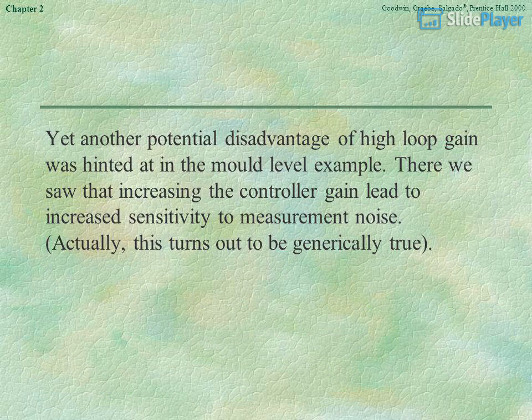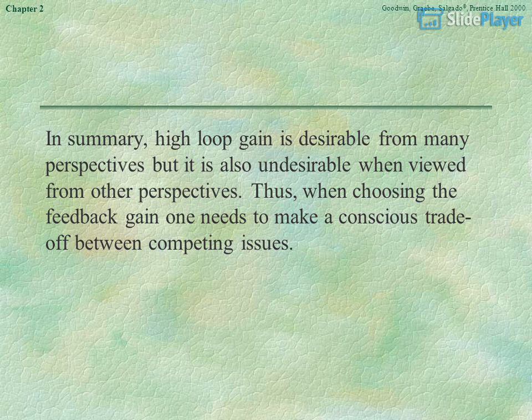Yet another potential disadvantage of high loop gain was hinted at in the mould level example. There we saw that increasing the controller gain led to increased sensitivity to measurement noise. Actually, this turns out to be generically true. In summary, high loop gain is desirable from many perspectives, but it is also undesirable when viewed from other perspectives. Thus, when choosing the feedback gain, one needs to make a conscious trade-off between competing issues.